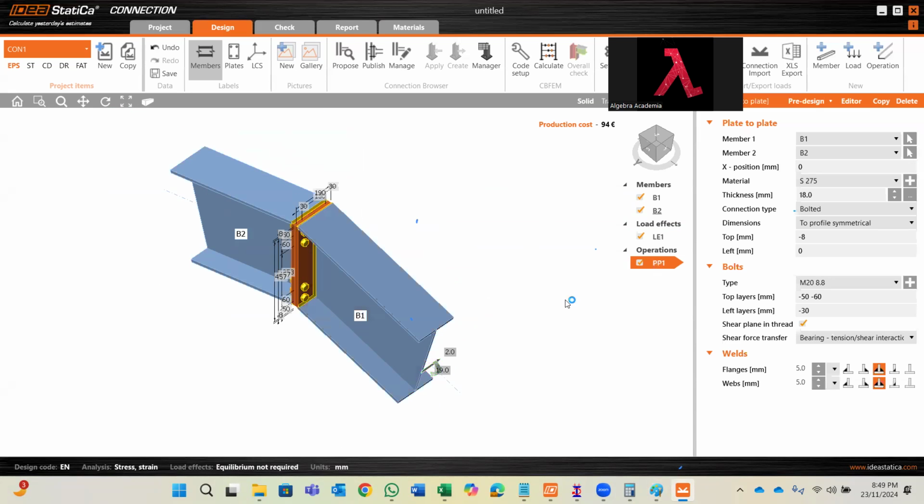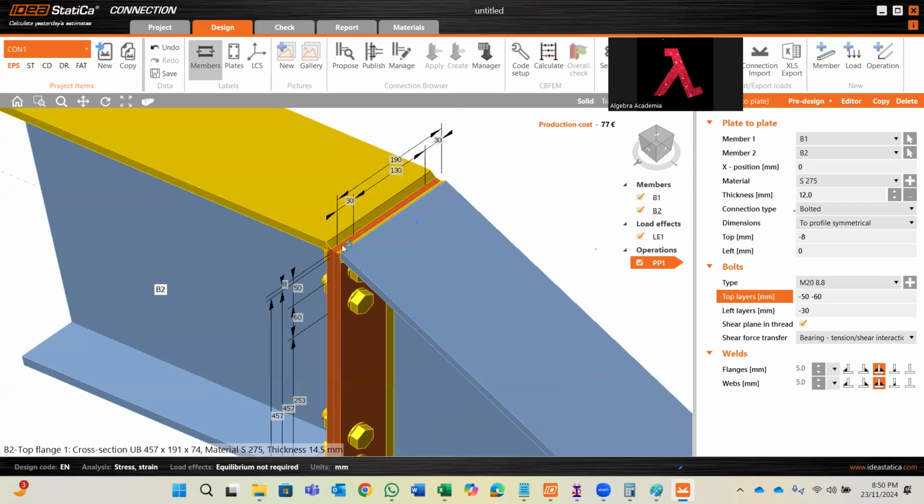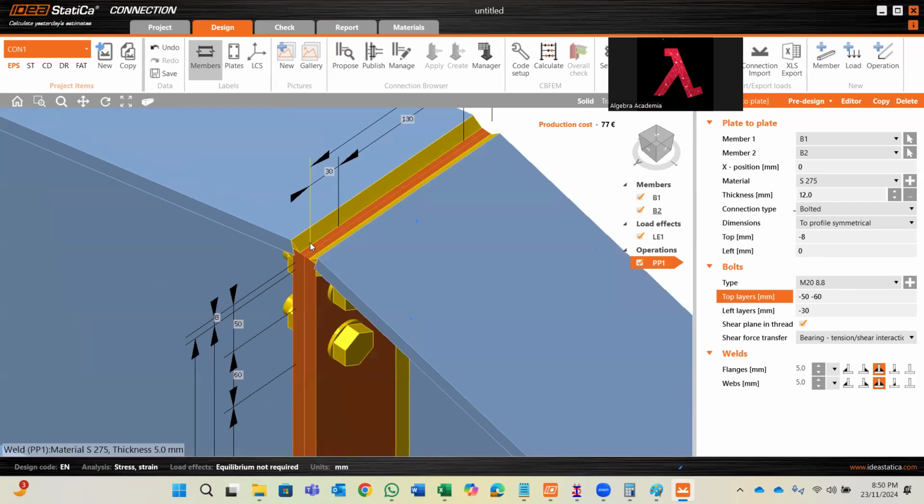Okay. And having the base plate, the thickness I'll change to 12 millimeter, the minimum thickness. And this is the top. In order to receive the weld thickness on top, you'll have a projection of minimum 8 to 10 millimeters, because we'll have the weld on top of it.